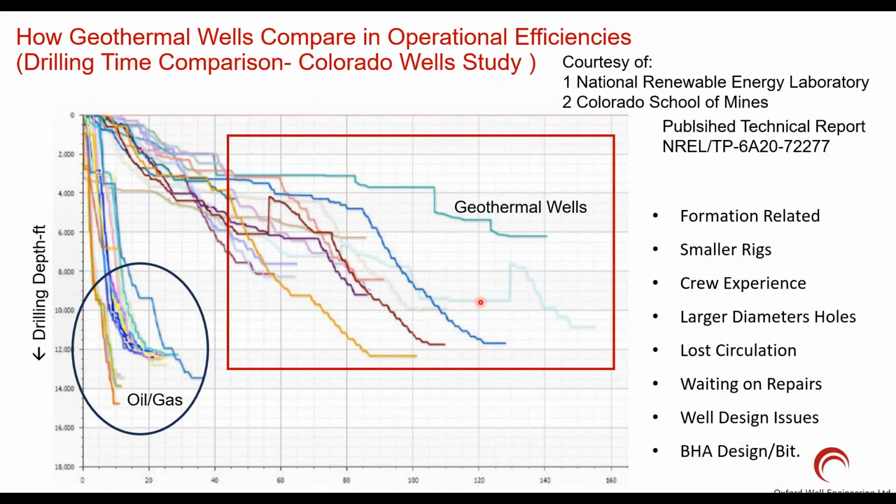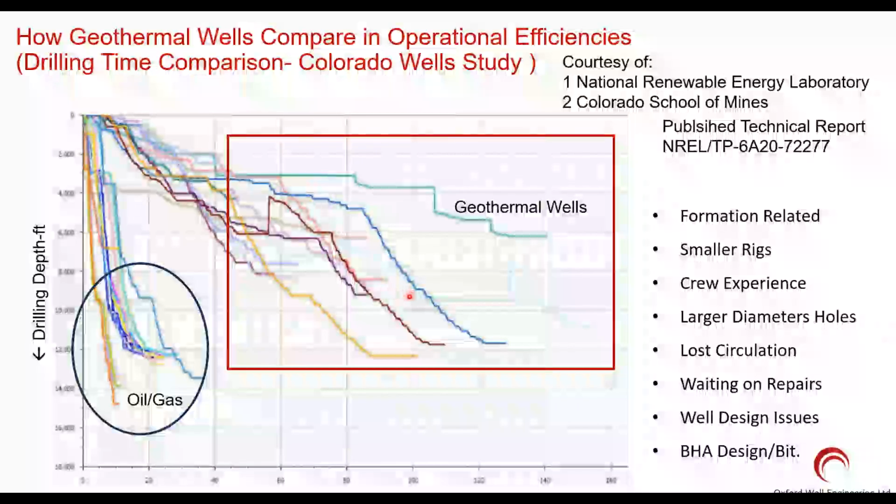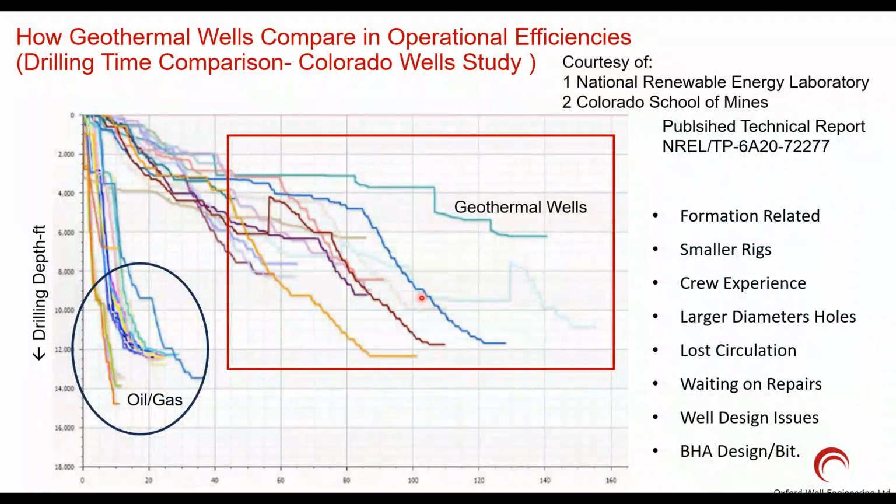They got stuck or something. Look at the character of these slopes. Step, step, step, and look at the character of the oil and gas wells. Not too many steps. Step means horizontal, vertical, horizontal slope, horizontal slope. Horizontal means lost time, flat time. People call it flat time in the drilling business. Flat time is bad news, but flat time is necessary as well.